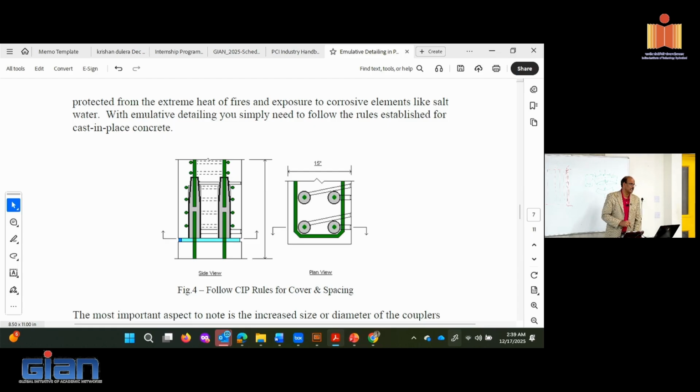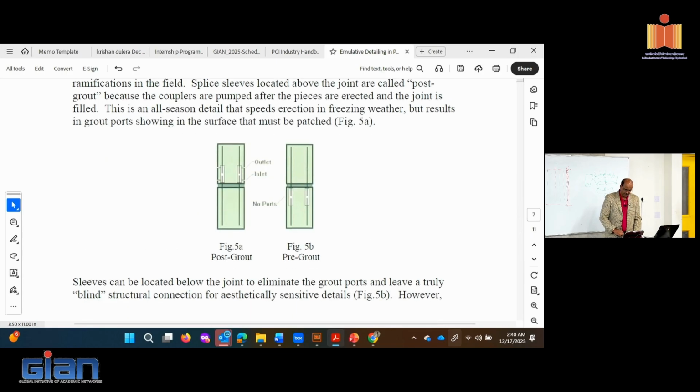They specialize in developing this coupler for different bar sizes. You could see it's narrower because this can be positioned in the factory and make sure the rebar is already in. This is a little wider because that's the receiving end. You have to have some tolerance, and they account for the tolerances. So everything makes sense in terms of how people can establish a connection.